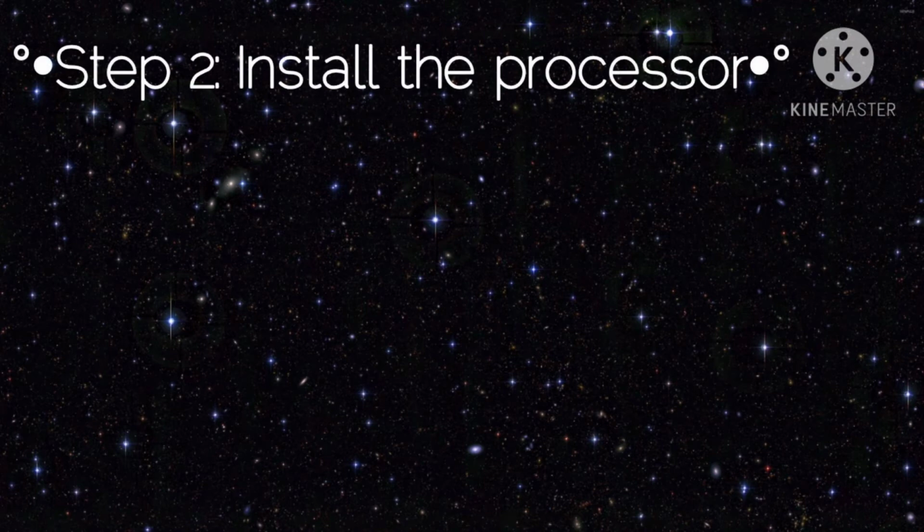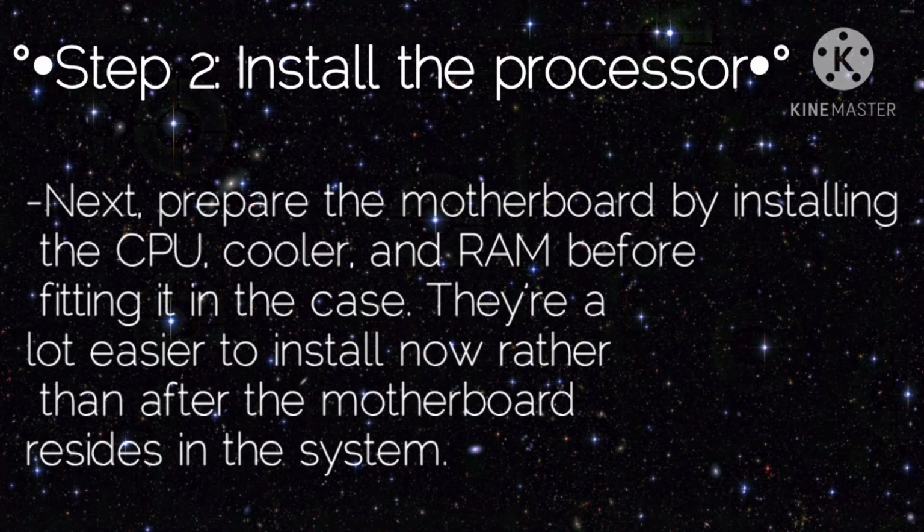Step 2. Install the processor. Next, prepare the motherboard by installing the CPU, cooler, and RAM before fitting it in the case. They're a lot easier to install now rather than after the motherboard resides in the system.